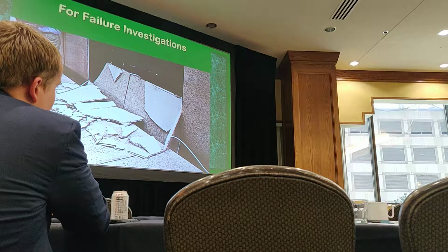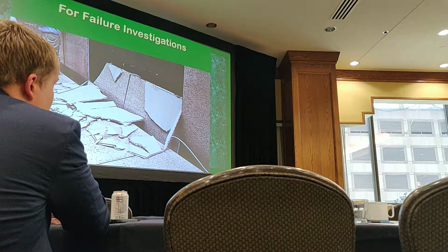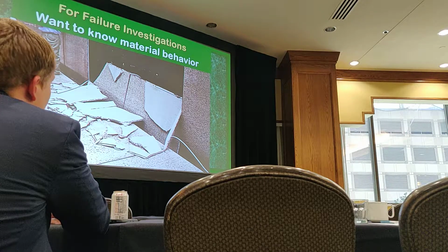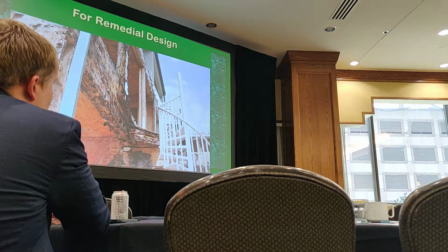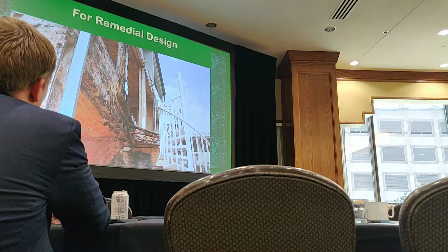Well, we do care about what happened, and that's the first practice area that we come to this subject from, is failure investigations. We need to understand material behavior in order to investigate why failures occur. The second major practice area is that we're going to design a solution for these failures. So here the brick masonry has been entirely removed. You can see an abject failure of the structure behind it due to trapped water behind the masonry.